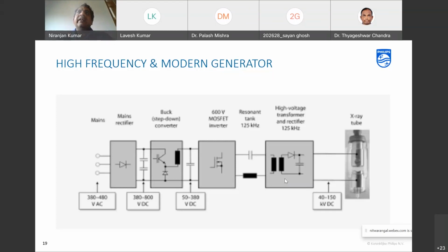We generate very high kV so the characteristic of the X-ray is totally different. Once the material is finalized, we can find what characteristic of X-ray is required, and in your case it will be a little higher kV, I believe. Maybe for a crystal around 180 to 200 kV.